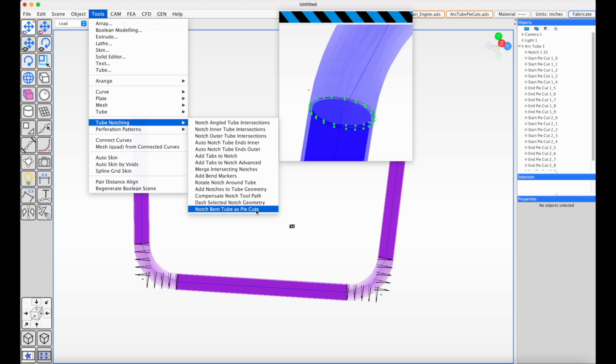So this is the new tool that we'll be using in this video, notched pie cuts. The idea is that you can take a CAD model design of an exhaust or a coolant line or any kind of metal piping that you want to route in software. You can do the design and export G-code which tells the tube notcher how to cut it from each tube in one piece, and it will cut multiple slots. The slots will allow the tube to basically fold like a slinky, bend to shape, and then you can weld back together the gaps in between each of the pie cuts and reconstruct a complete tube with your shape. You don't have to take lots and lots of pie cut pieces and assemble them together. You can do it in CAD, cut the whole thing on the machine, and then fit it and weld it.